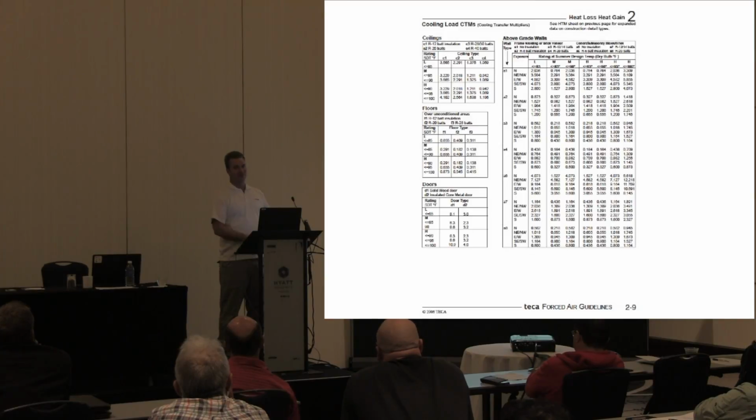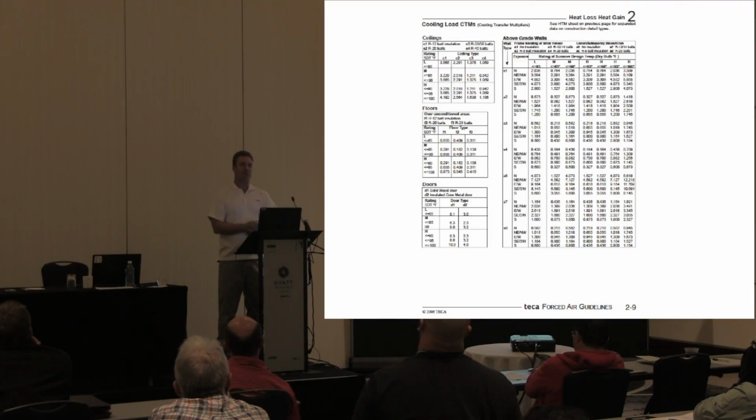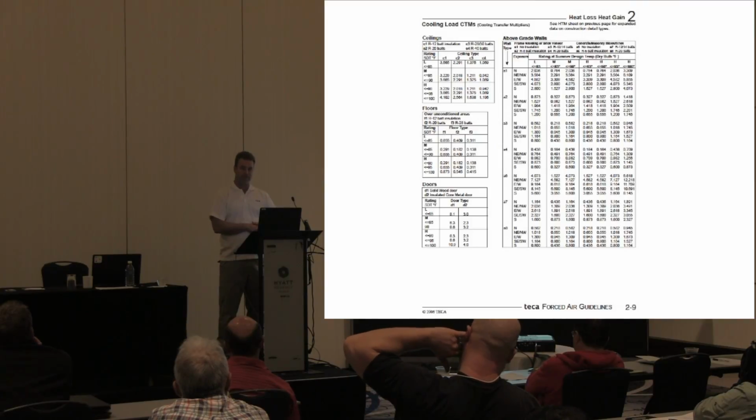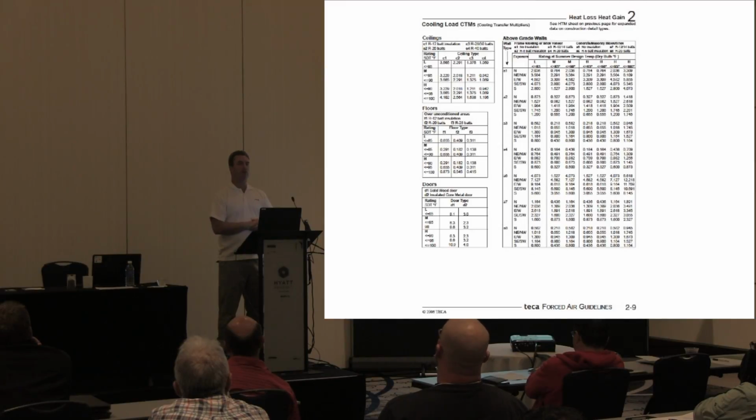Yeah, no. And they put a gas backup in, or electric backup, it doesn't really matter, but say they use gas. So they put a 40,000 BTU gas backup in, which is more than the 36,000, so they'll easily meet the heat loss. The problem is they set the system up so the heat pump runs, because wherever they live, it's way cheaper to run the heat pump. And then what happens is that 3-ton heat pump that's 36,000 BTUs at 47 degrees Fahrenheit outside is now only 20,000 BTUs at 17 degrees Fahrenheit, and that's where the design temperature is. So you're 14,000 BTUs or so less than what you need.